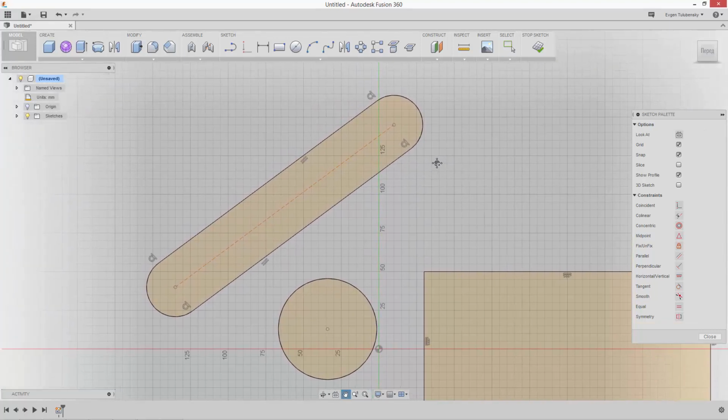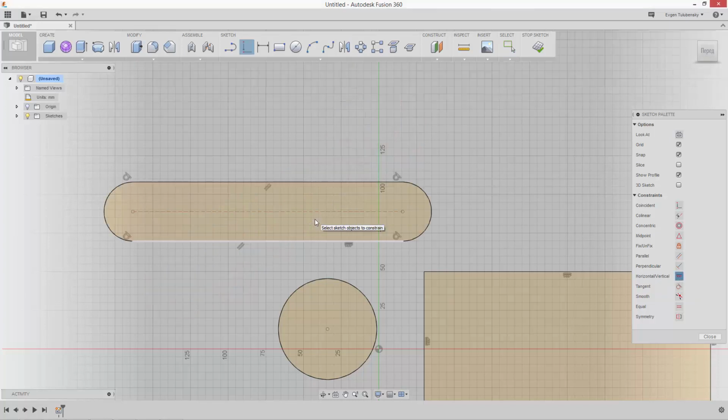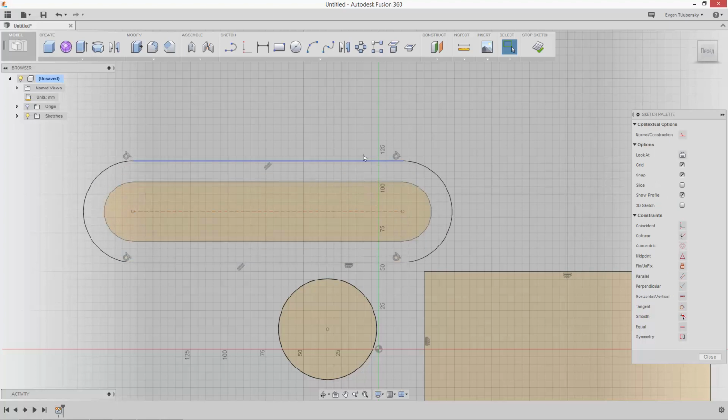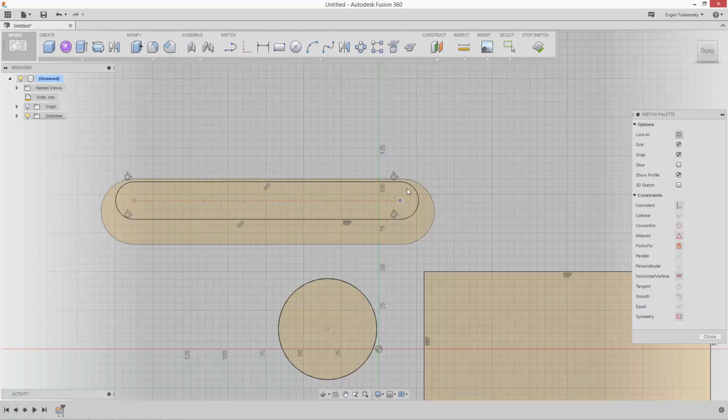You will notice the various symbols that are being created on the geometry. These are constraints. They control the relationships between the entities in the sketch. Look at the Constraints panel on the right side. Select Horizontal/Vertical Constraint. Select one of the straight lines in the slot. The horizontal/vertical constraint sets the geometry to whichever is closer, horizontal or vertical. By adding a horizontal relationship to the slot, we have fixed its movement. Try dragging on some of the points to see the behavior.